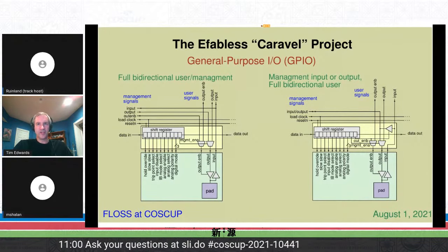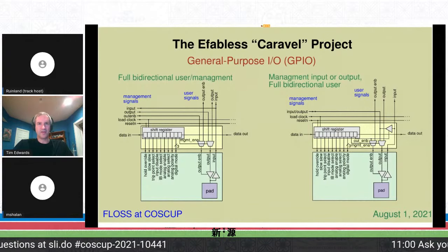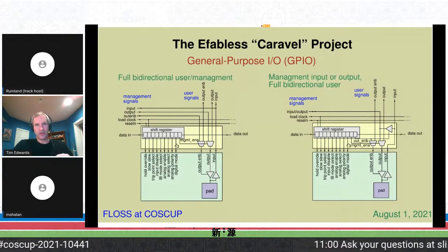In addition to the basic pad configuration, there's also a control signal that determines whether the pad is under the control of the user area or under control of the microcontroller. When pins are under the control of the processor, a number of pins have specific functions for use by the processor, such as additional SPI interfaces, an I2C interface, a UART, external interrupt, and monitoring of select internal signals. The user project designer can opt to let the pins be used by the processor or leverage them for the user project.